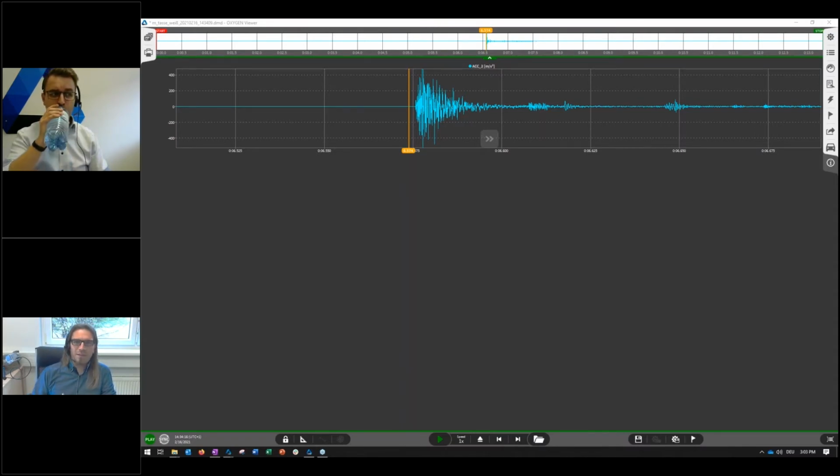And the problem here is that the data rate of the high-speed camera is so high, it cannot be transferred from the camera to the PC during the measurement, but it can only be stored to the RAM available on the camera itself. And this video can be exported later on when the camera data acquisition is finished, and afterwards loaded into Oxygen and synchronized to the sensor data, to analyze and review the sensor data in parallel with the video data. And how that is working, to import the external video into the software, I would like to show you.